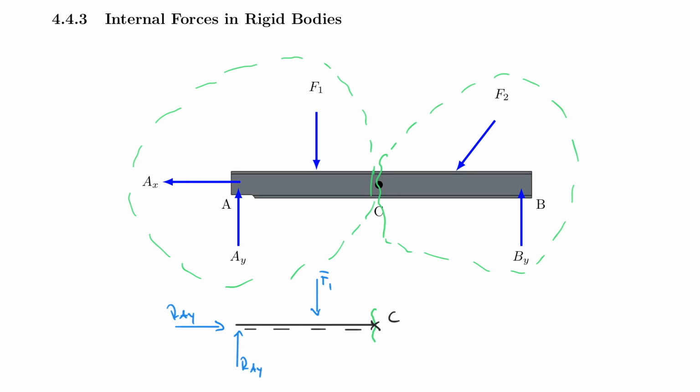And this system, of course, cannot be in balance because, yeah, maybe F1 is equal to RA1 and then it would all be in vertical equilibrium. But again, you would have rotation, so it cannot be. And by the way, F1 here would not be equal to RAY unless it would be a very special case. And therefore, there's not even a vertical equilibrium. So what you have to do is you have to bring in your internal forces, which now, by the way, are external forces, right? So by me cutting the system here, and sometimes I give this a name, like I call this here cut 1, and I call this here cut 2. And of course, here I have given cut 1.